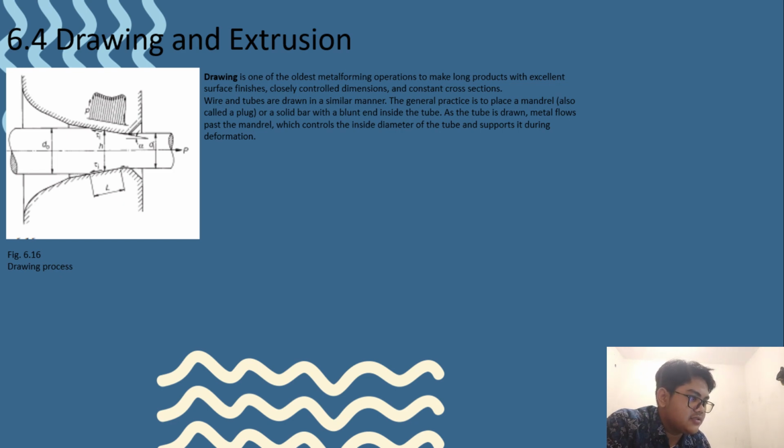We got hot extrusion technology. Pre-rolled billets or round ingots can be worked in an extrusion press with an open-ended die. The press forces the metal through the die, which determines the shape of the extruded shape. For hot extrusion, the billet temperature is typically greater than that required to sustain strain hardening during deformation.